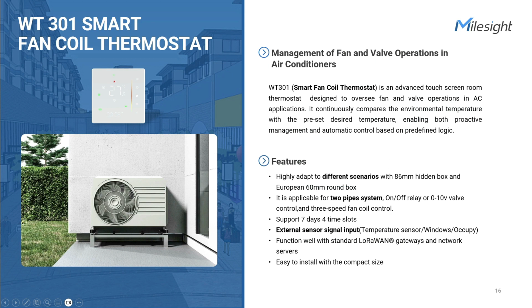And the third product is WT300, an advanced touchscreen room thermostat. You can access parameters such as system mode, fan mode, and temperature set points. Valves and auxiliary electric heaters can be controlled using a relay or a contactor system switch controlled by the thermostat. What I want to emphasize is that it works with either a 0 to 10 voltage proportional integral valve or a 2-wire on-off motorized valve.